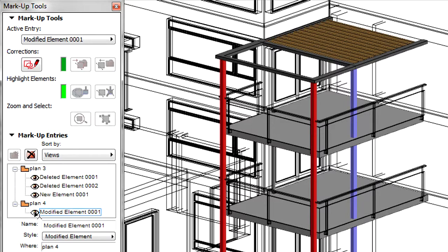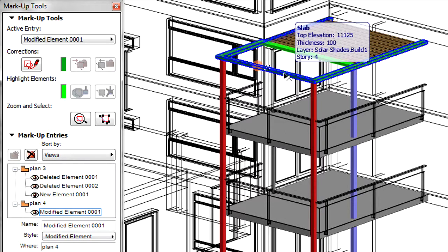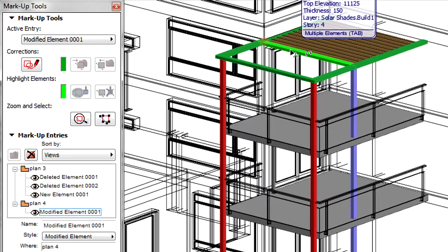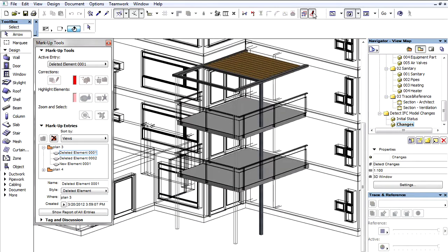As you can see in this example, the solar shading system of this balcony part has been modified, reduced. 2 columns were deleted, 1 new column was added, and the roof size was modified by the structural engineer. Then we can accept or reject the changes suggested by, for example, the structural engineer in the architectural and/or referenced model environment. Let's see how constructors, consultants, owners, and clients can also join OpenBIM.